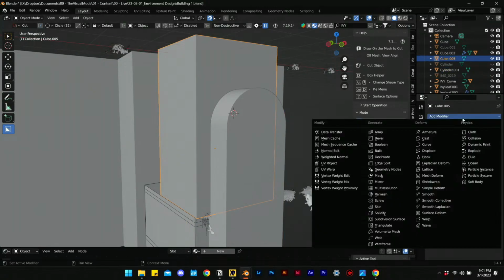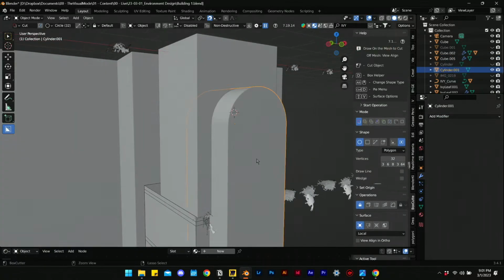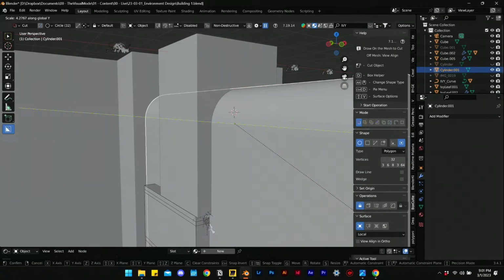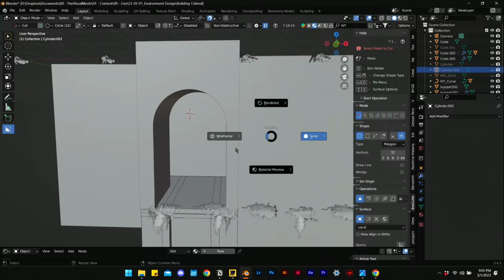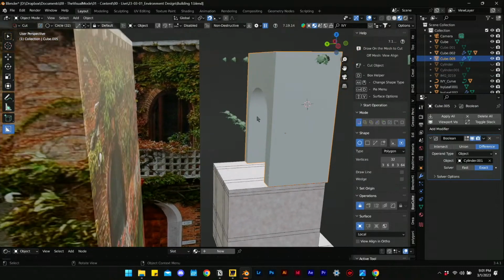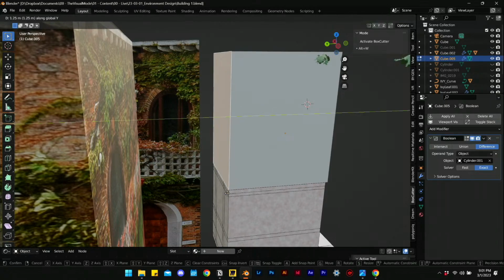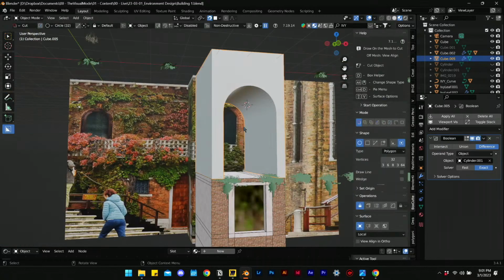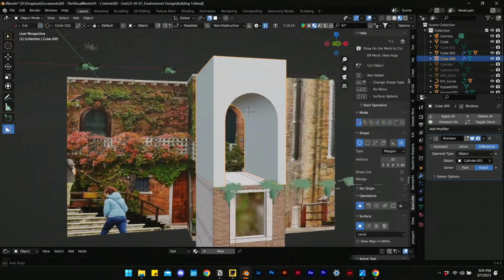Select this one, Boolean modifier, difference with this one, and there we are. Trying to use these fancy plugins, these different methods, but we have an archway. We're really just gonna use this photo as reference at this point. I can move this face over. Don't worry about the arch going away. It's just still a modifier. We'll do face project on a snapping, and there we go. Tab back in. We have our arch. I'm only going to...